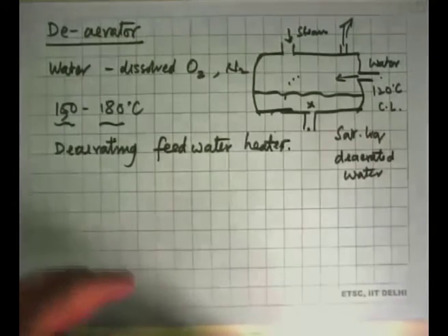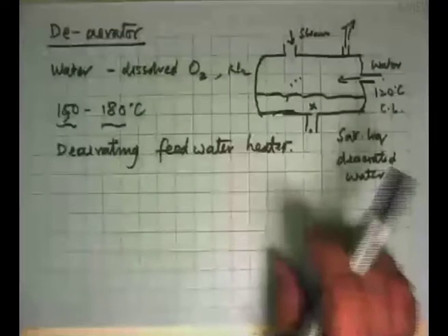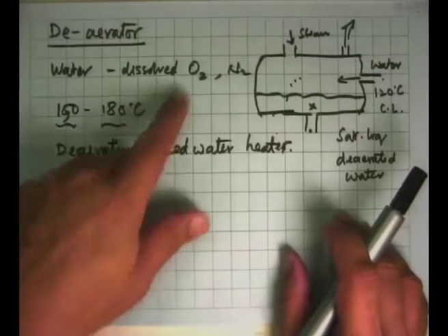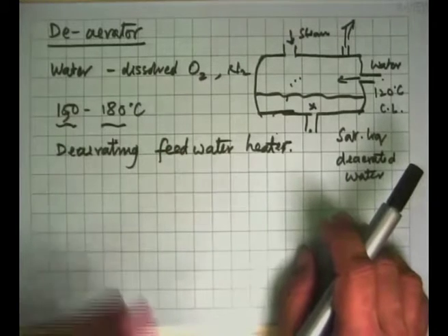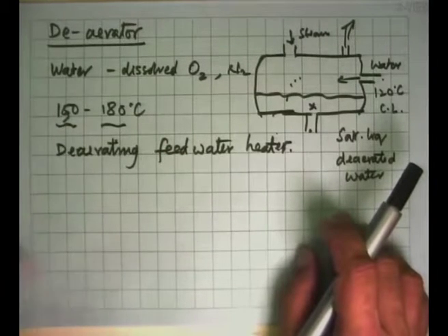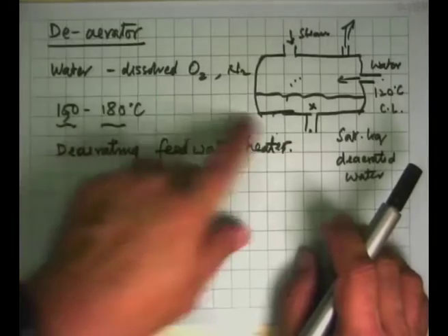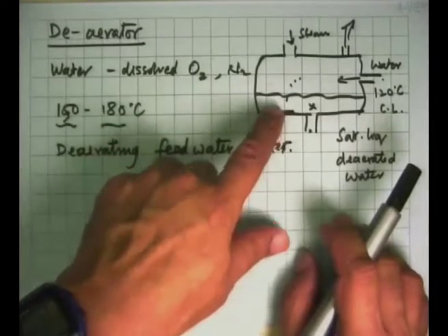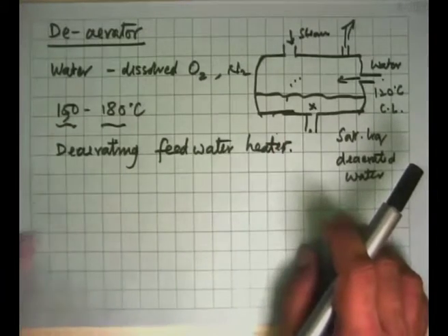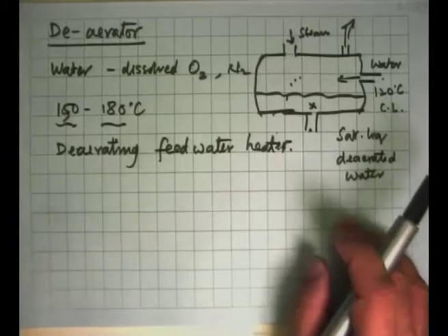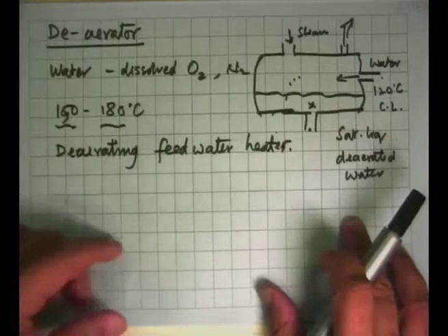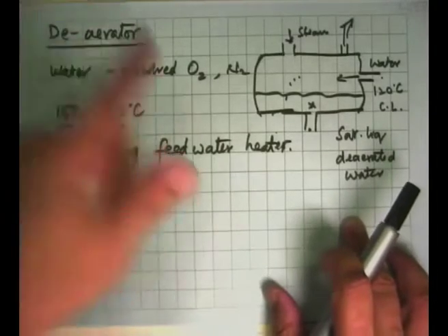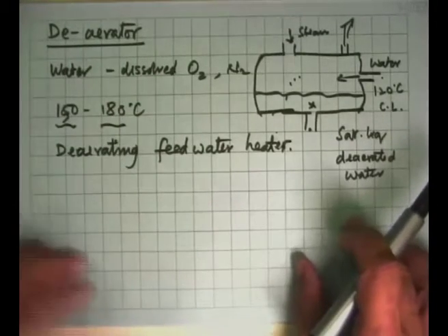And the higher the steam temperatures that one employs, the less is our ability to tolerate dissolved oxygen in the water. So as you go from 550 degrees Celsius to 600 to 700, we have to remove much more oxygen out of this water than what we have in, say, conventional power plants. So that's one of the engineering challenges: if you want to increase the thermodynamic efficiency by going to higher temperatures, the oxygen dissolved in the water has to be brought down. There are a different set of things that one needs to put in place.